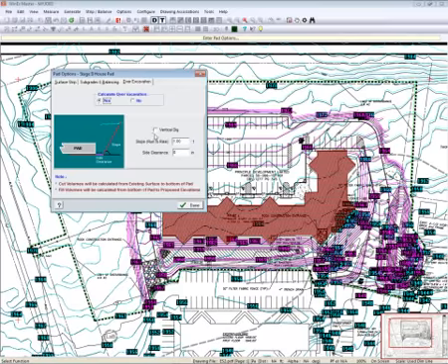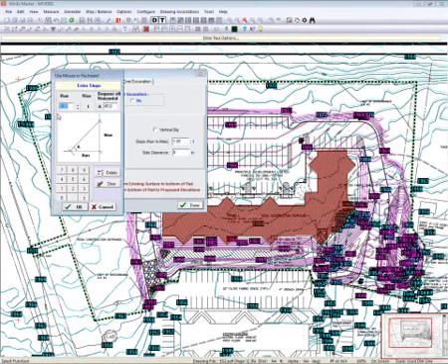Now, you could do a vertical dig. In this particular case, I'm going to choose to do a slope with run to rise. And maybe I don't want a one-to-one run to rise. So I'll click in there, and I can change either the run to rise or I can change the degrees off horizontal. Either one will automatically configure the other one. So let's say I want to make this a 35-degree off horizontal. You can see it automatically changed my run to rise.